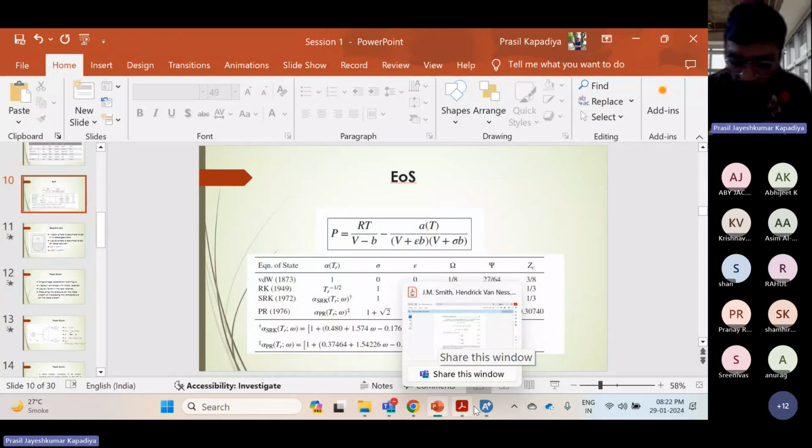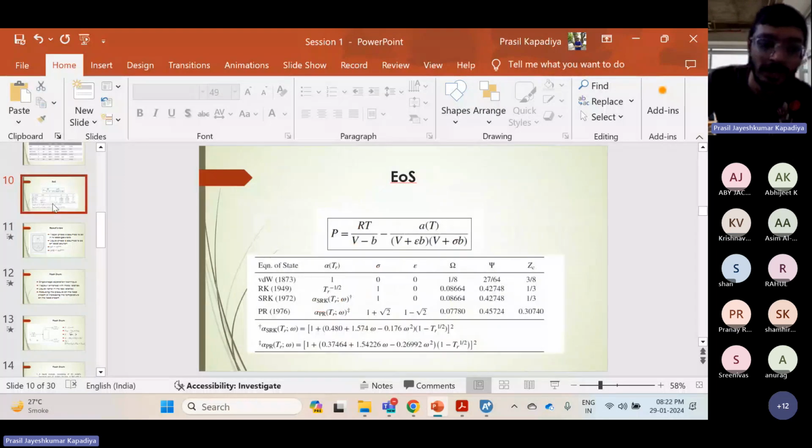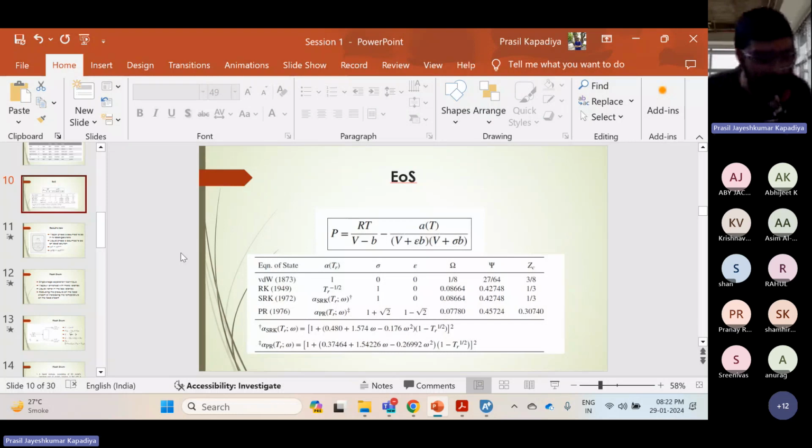Currently I'm pursuing my research work on some phase equilibria diagrams. From my experience, I can see that the VTPR equation of state is currently the best, predicting near to what it should be. That is volume translated. If you know the SRK, PR, RK equations of state, they don't have Vc terms in the equations, but the VTPR equation of state additionally takes the Vc term, that is critical volume. That's why it is called volume translated Peng-Robinson. I will frankly say I don't know the VTPR equation, but you should know the concept.